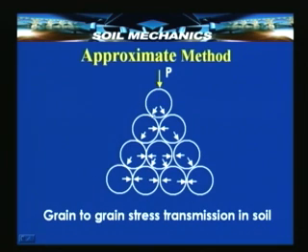See here, the stress gets divided between these two. These two particles in turn are supported by 3 more particles here like this. So, this transmits stresses here as well as here as well as here, and this goes on and on. Ultimately, this load P gradually gets dispersed over larger and larger areas as we go deeper and deeper. That is a very important finding. This shows that this load P acts on larger and larger areas as we go deeper, which means the stresses per unit area go on decreasing with depth.